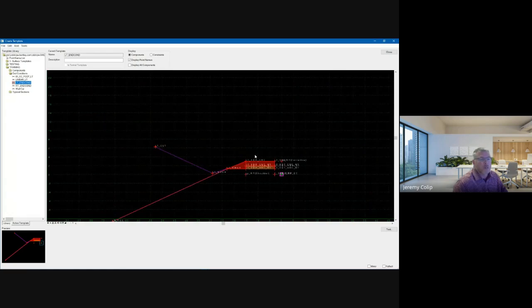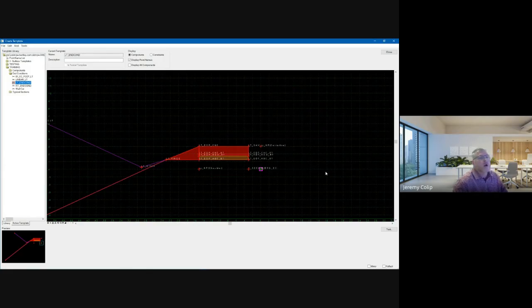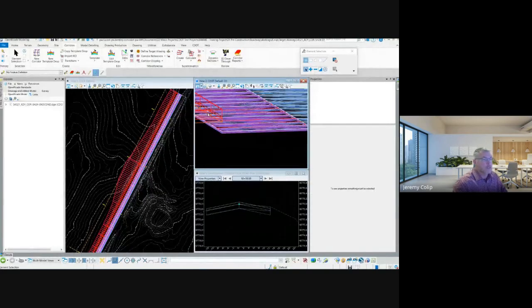So this is one thing when creating templates and stacking those so that you can see them independently. I said, okay, I want a vertical offset from my control so I can start to see all my different elements. That's why that has a 3-foot offset. I could start this at 0, which is fine, but I just made sure I offset those other ones. Since it has that offset, you saw it's up above my other corridor, so I want to bring that back down.